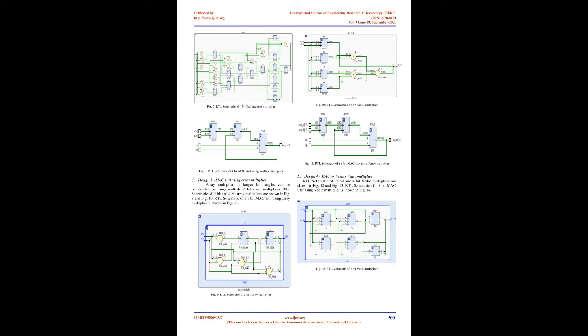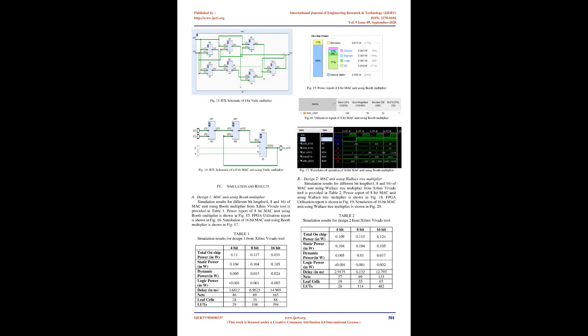B. Accumulator. The accumulator is a register which stores the sum of products. It is widely used in arithmetic logic units (ALU) and MAC units. Storing values in the accumulator can eliminate the need for additional summing operations. The response of the accumulator should be fast enough to match with fast adders. Parallel in parallel out (PIPO) shift registers are widely used as accumulators as they are fast and give output within a single clock pulse.